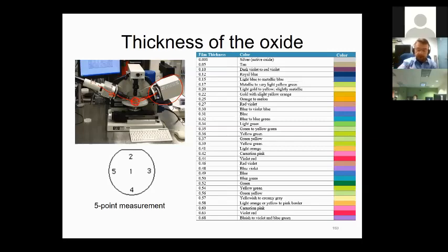That wafer, based on its characteristics, the thermally grown oxide on it or thermally grown nitride on it, will alter the properties of the reflected light, and the photodetector will do some reverse engineering to sort out the exact thickness.